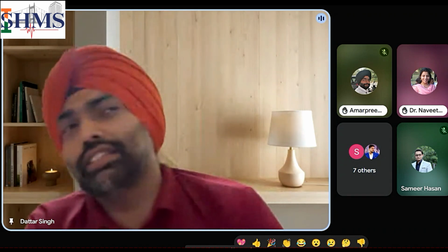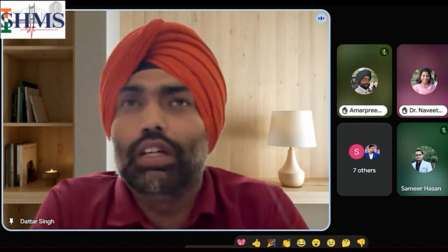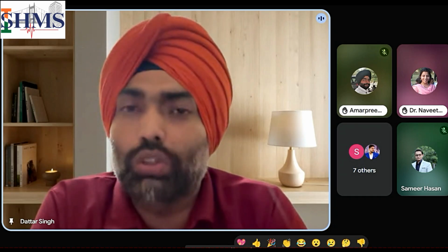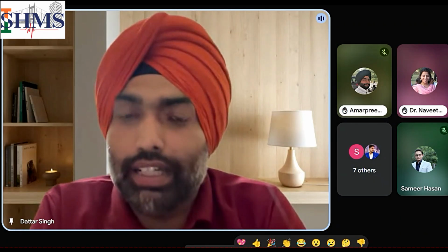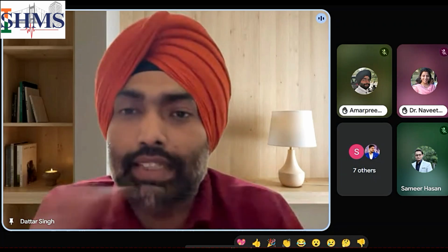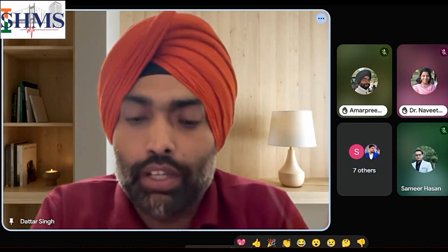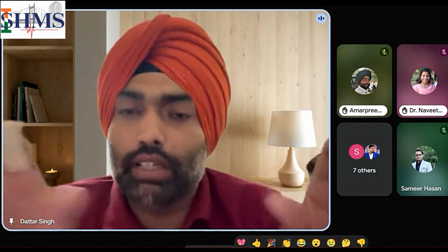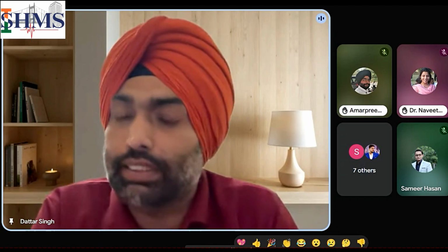Ma'am, the reason behind this could be that concrete structures are a little more stiff than steel, which leads to a little less deformation, so data signatures can be captured more easily in steel structures. Secondly, to differentiate between numerical modes or data noise and actual modes, we need mode shapes. Say we have 8 sensors placed on the bridge, 4 along both directions. The actual modes corresponding to structural modes would be at the peaks in all the sensors, not just one sensor.